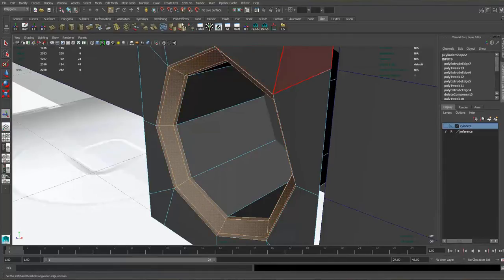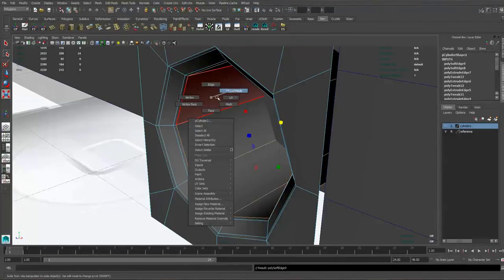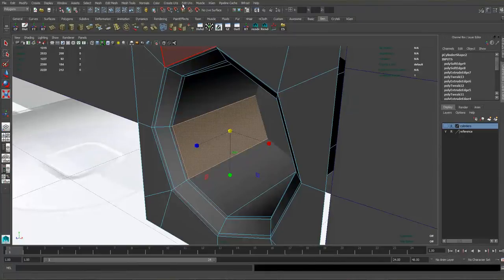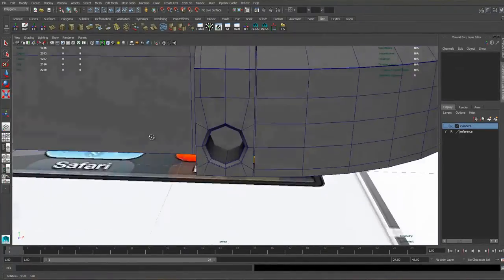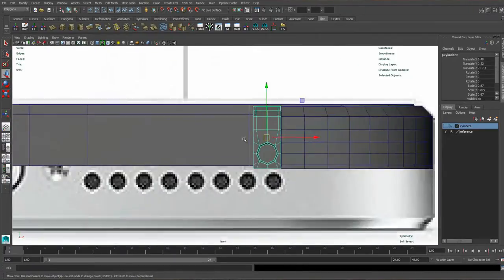and then I could probably just go to smooth edges, and I could probably double click my way around there, and again smooth edges. If you don't have the smooth edges, it's in normals, soften edge, and it should look quite nice now. Now we are free to duplicate this, so we could set up a duplicate special command, but